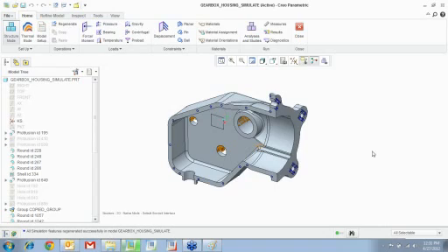Let's say I'm running a complicated FEA analysis. I am going to set up a bunch of different loads acting at different time steps. Now, I don't know if I set everything up right. So as a quick check, we can use a quick pass or the single pass to run it really quickly, get to see the animation and the displacement values or the stress values and see if we have defined everything correctly. Once we decide that, okay, everything that we defined is correct, then we can set more stricter criteria and run a more stricter analysis, like say a multi-pass analysis.